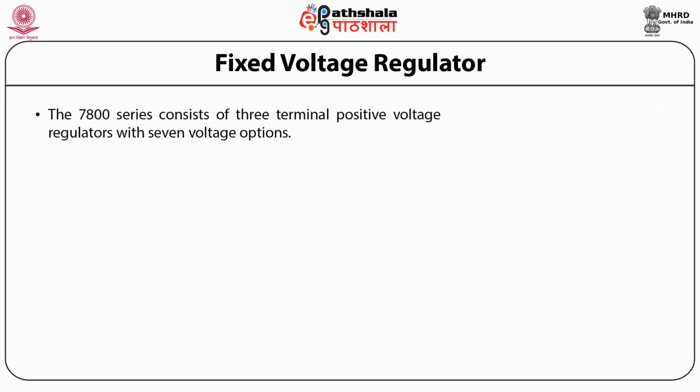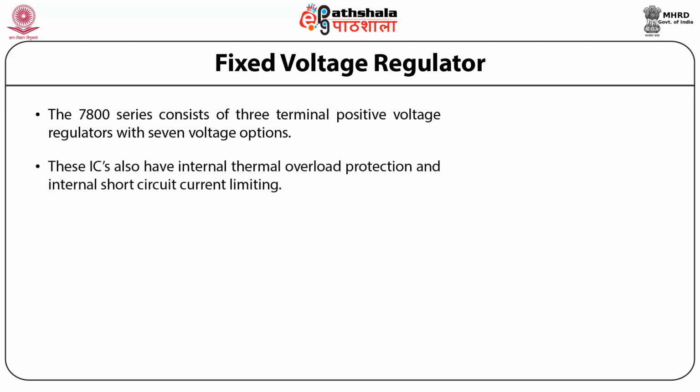Here the 7800 series consists of 3-terminal positive voltage regulators with 7 voltage options. These ICs also have internal thermal overload protection and internal short circuit current limiting.